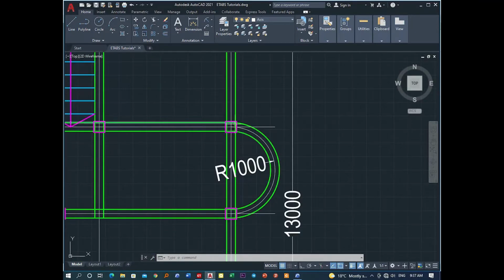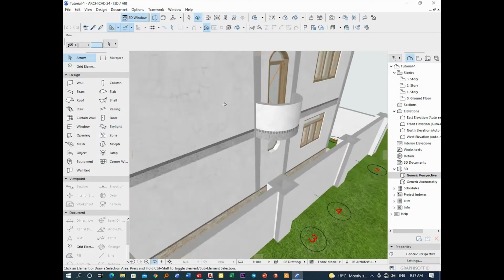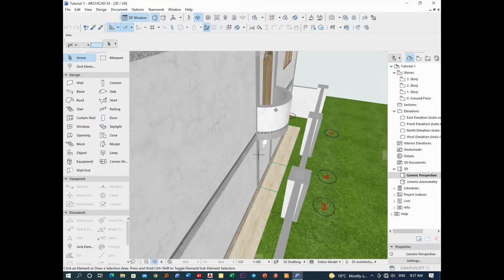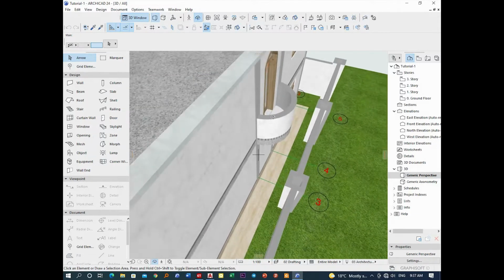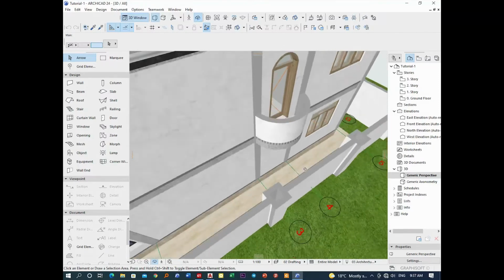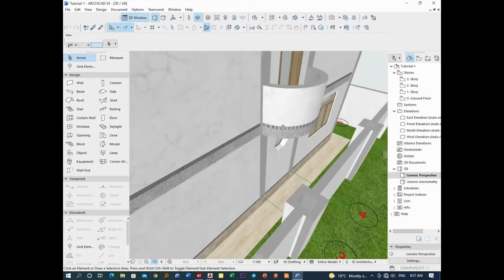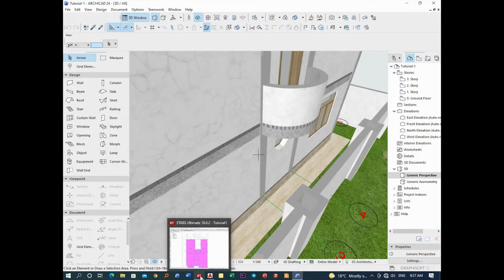Now, I will show you this simple example, okay? For this curved beam here, and I have a slab here over here. Let me show you the 3D view, okay? So this is a simple balcony here, okay? So I have a beam here, and over it I have some kind of slab here, okay? So I'm going to create this curved shape using a cylindrical grid system, okay?